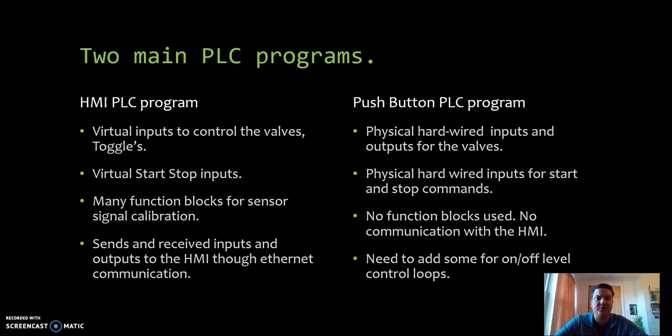So the push button PLC program has physical hardwired inputs and outputs for the valves. Although the PLC program for the HMI has hardwired outputs for the valves, there is no physical hardwired input for those valves. All right, we also have physical hardwired start and stop buttons for the PLC program that works through the push buttons. We have a normally open green push button that's used for the start command, and then we have our physical two-position selector switch, which is used to enable the VFD and also start or stop the pump.